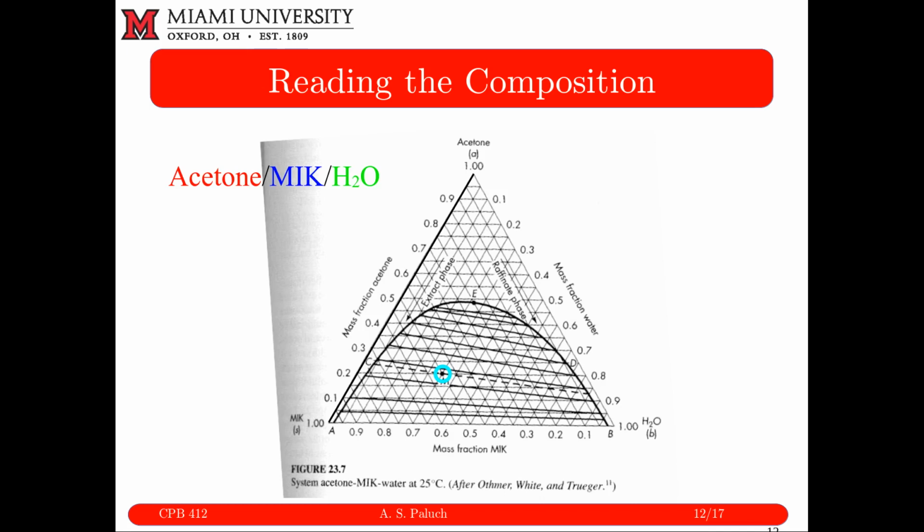Okay, so instead, what we need to have on our phase diagram are called tie lines. Okay, so you'll see a bunch of these lines drawn that connect the two sides of my miscibility boundary, or my phase envelope. These are called tie lines, and those are experimentally determined. If I'm in the two-phase region, I'm going to get phase splitting along a tie line. Now the challenge is, tie lines are not just isotherms or isobars. These would have to be determined experimentally, right?